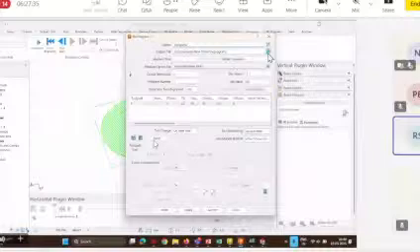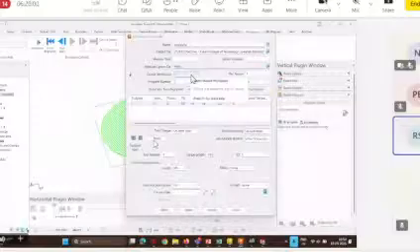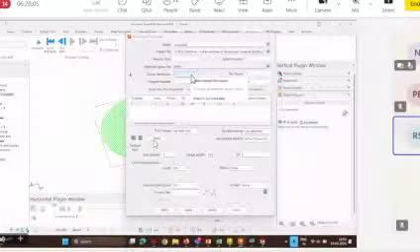Then you have to specify the machine option file. That is nothing but your controller. So like I said, every controller accepts a particular file extension. So maybe you can select Fanuc one and click accept. And then you can select the output work plan, because if you're doing 3+2 deposition, like you index to a certain position and about that only you want to deposit that three axis strategy, then in this case you have to select the output work plan about which you want to generate the NC file. So you can select from here, then you just click on apply and click on write. So it will generate the toolpath.